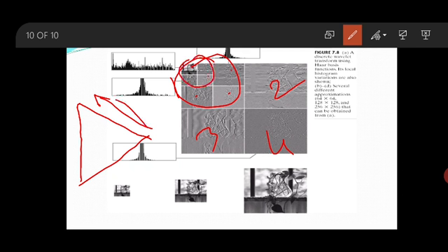It is as if you are downsampling the image. Now in this one you can again perform the same operation, downsampling; 3 you can perform here, 4 you can perform here. You are operating the wavelet transform on the full image. Once the operation is completed, we need to reconstruct. The smaller components on which you performed the wavelet transform, you reconstruct from the apex to the bottom, meaning upsampling, to reconstruct the image.